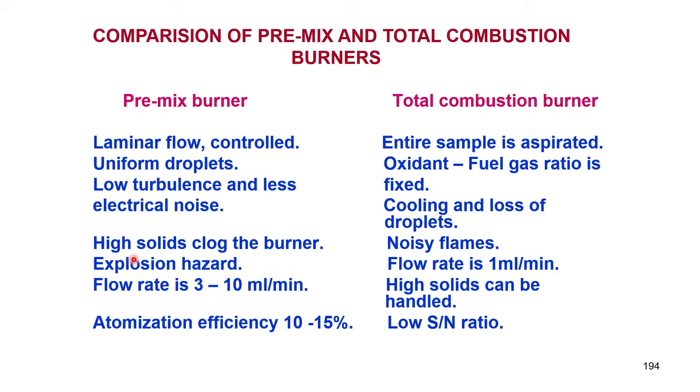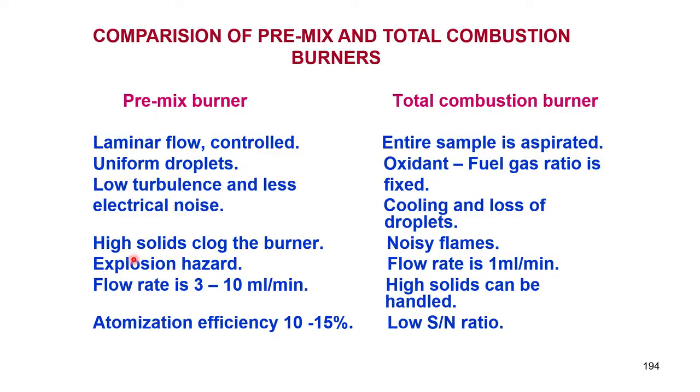And then because of the small size of the holes, if I have a solution, the particles, when they are coming out of the burner, encounter a heated burner. So, the liquid will evaporate, the solid will clog the small holes. This you must have seen even in your houses, where LPG burners get clogged and you have to clean them mechanically. So, in a premix burner you cannot use a sample with very high solids content, it has to be very low, and then if it clogs,